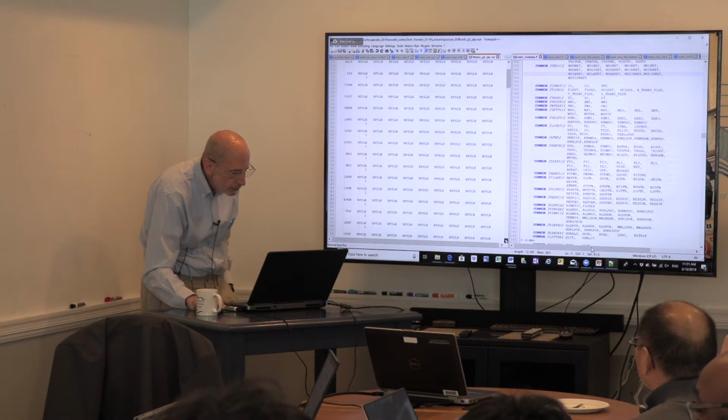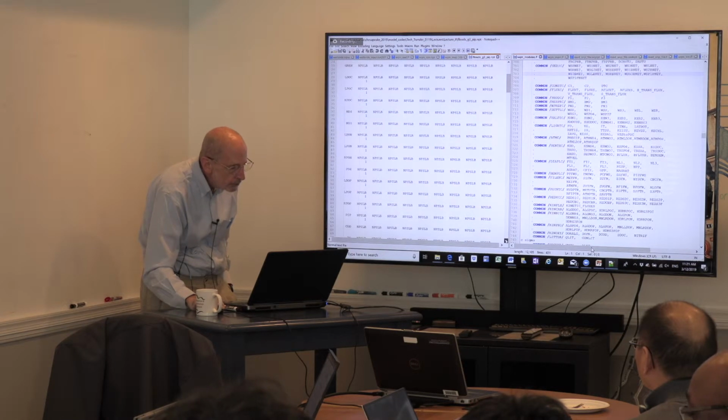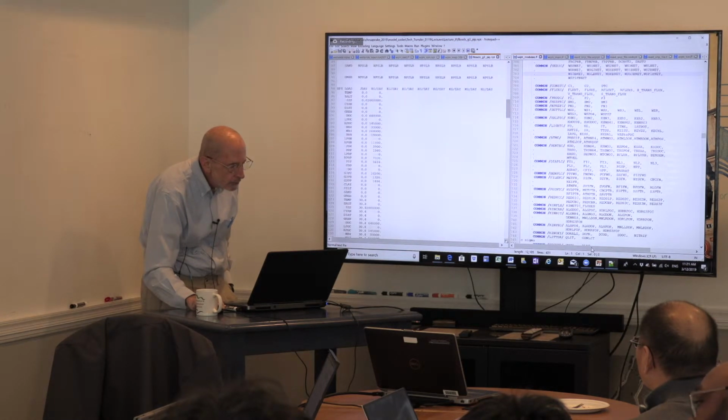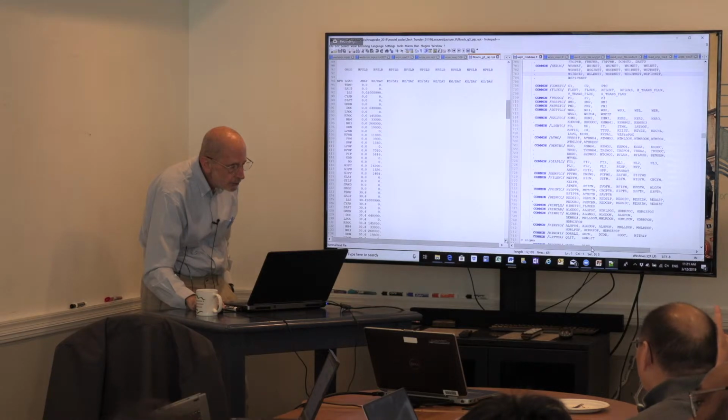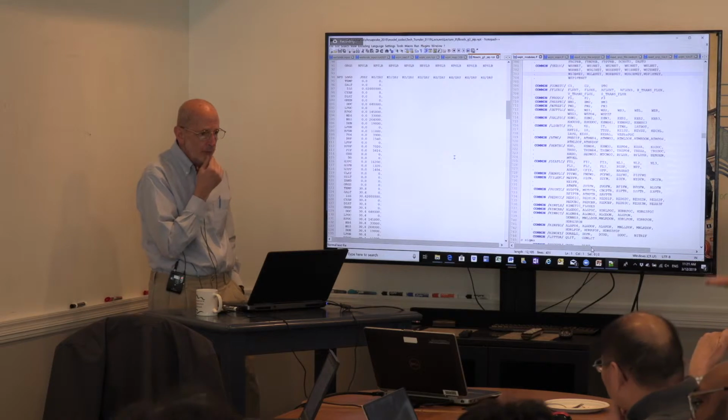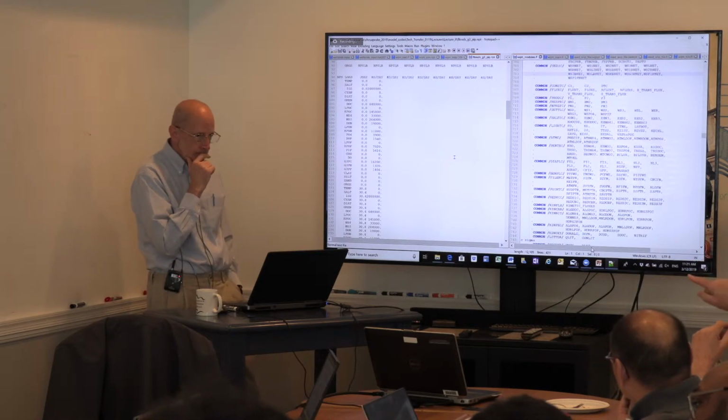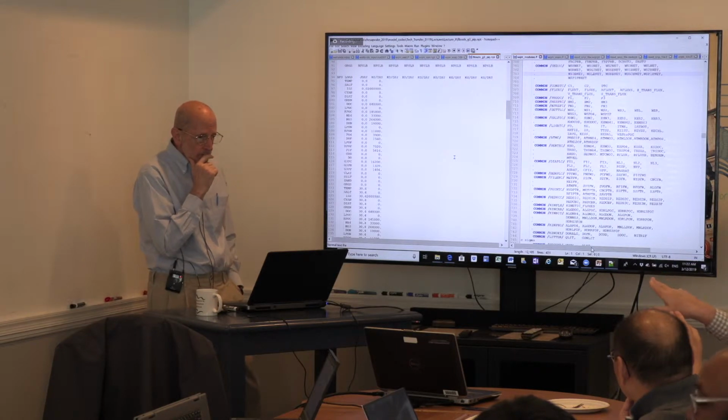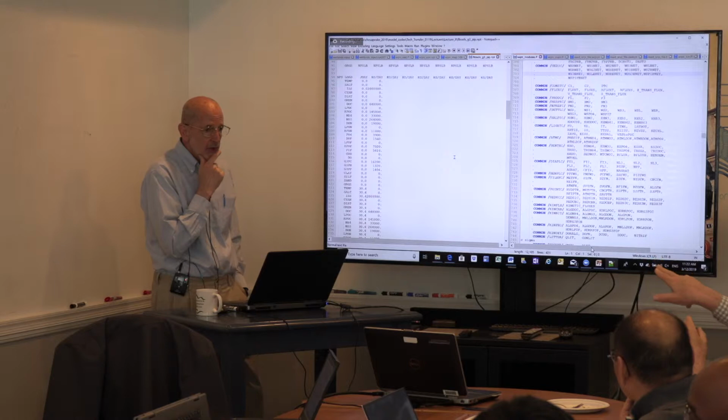I was going to ask if you had, for example, 1, 2. Right now you have 1, 2, 3, 4, 5, 6, 7, 8. So if you had 9 loads, you would need to use a second record. So on the second record, do you still specify temp and 0 and then the 9th load, or you just leave those first 2 fields blank? You leave the first 2 fields blank.